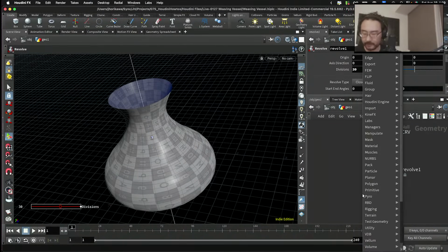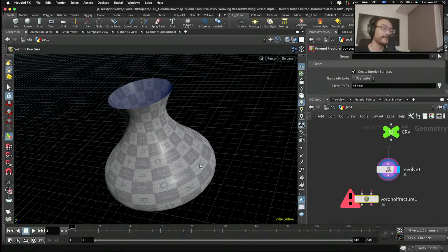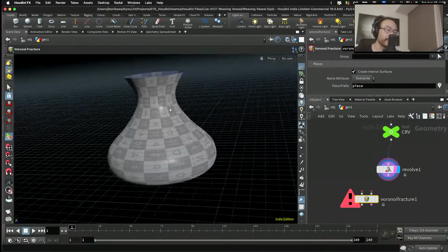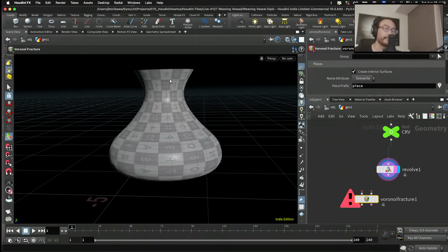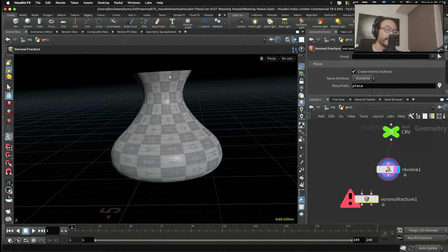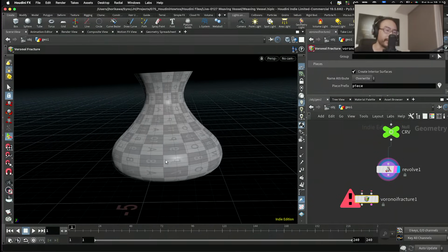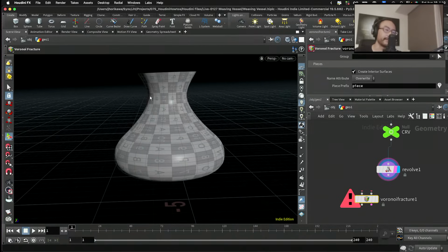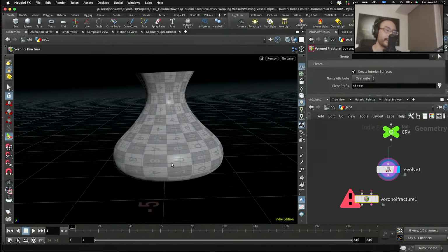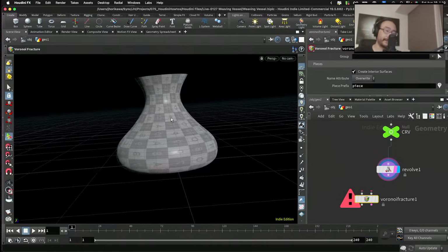the next thing I would like to do is to create a voronoi pattern on top of this surface, but I want to make a repeated voronoi pattern on this surface, meaning the pattern should be mirrored on a specific direction or specific view. For example, in this view, if this is the center line, then I want the left side and the right side to have the same pattern, so that it will look like a continuous, clean, symmetrical pattern.